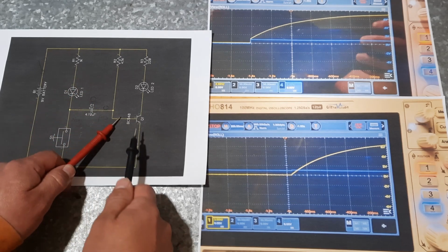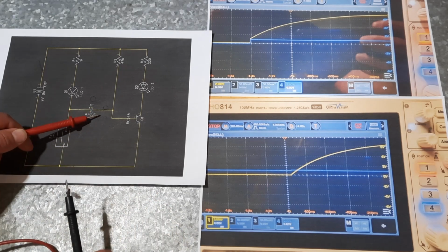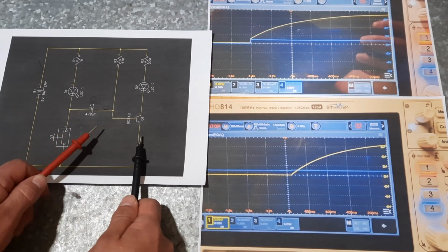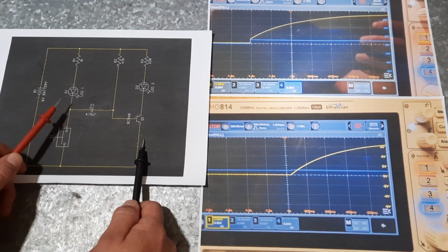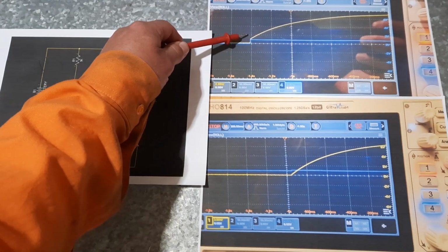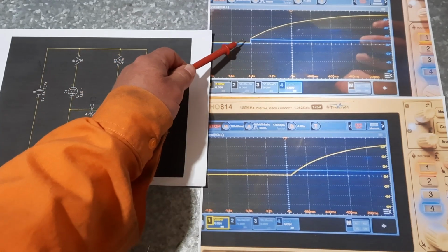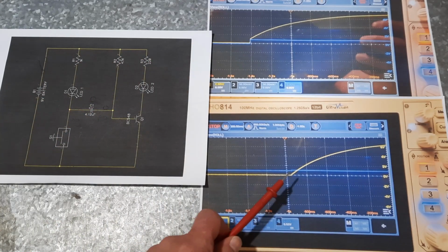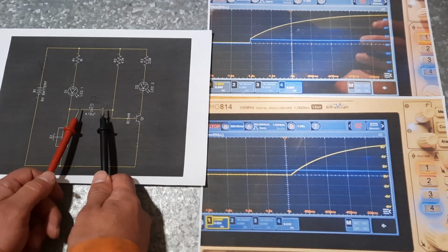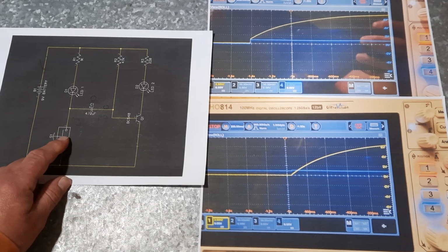So if we measure from here to here, there is still 0.7 of a volt there, and that's what's raising the floor of this cap. So 0 plus 0.7, this volt drop, when we very first turn this on, is what's causing this to shoot up, because that's the floor of that cap being raised by 0.7 of a volt. What's happening here?